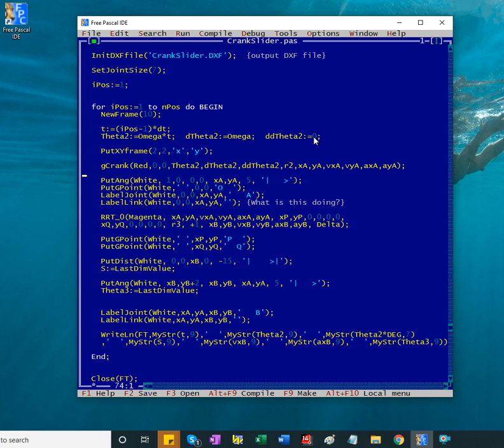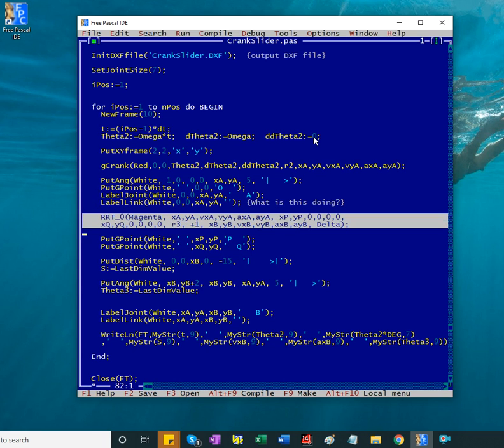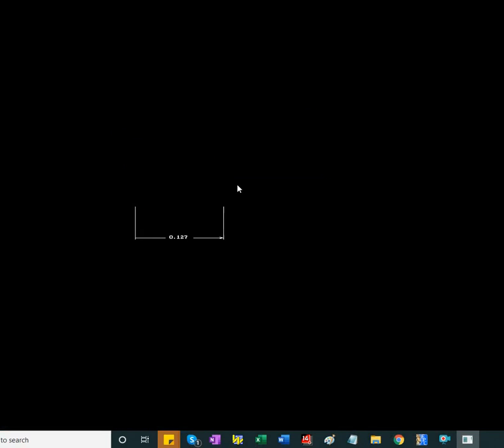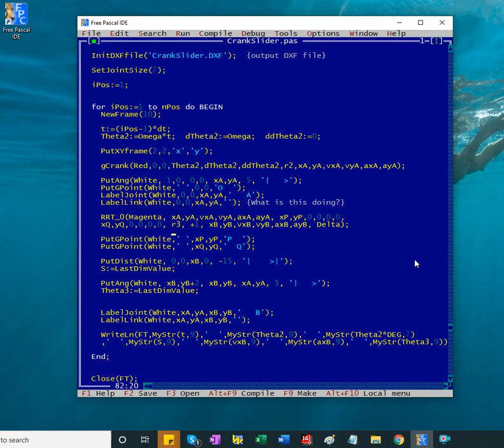You've seen this. Again, I took the link off, so there's no shape moving with the crank. You've seen this one, and this one. This is new, and very important: this is the Assur group, a simplified version of it. That's why the 0. A more general one would have an offset between B, the center of the slider, and where joint B is. But this is a centric dyad, RR prismatic, or RR translation, rotation translation.